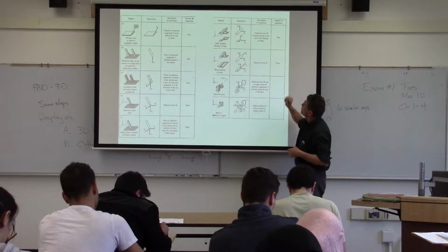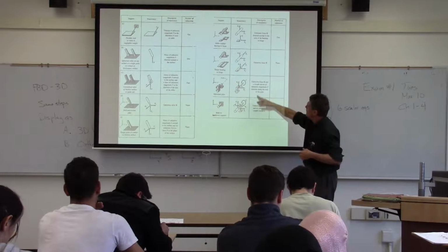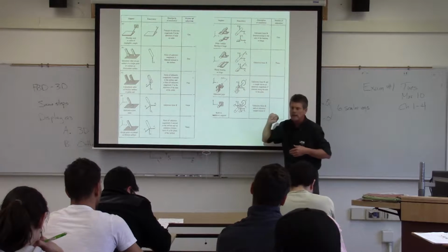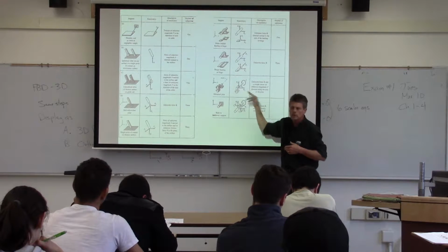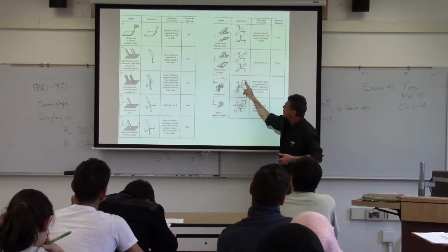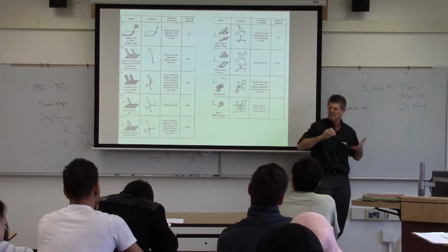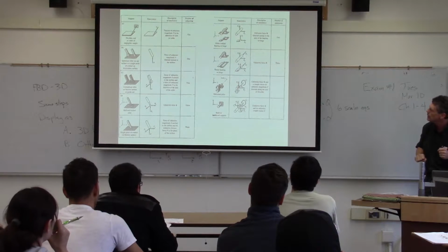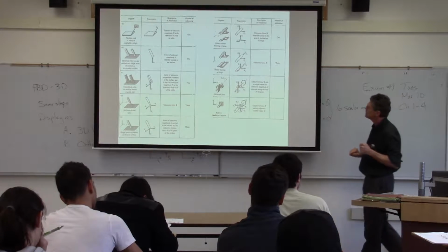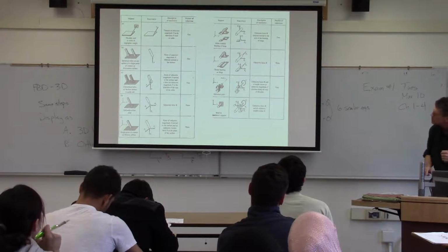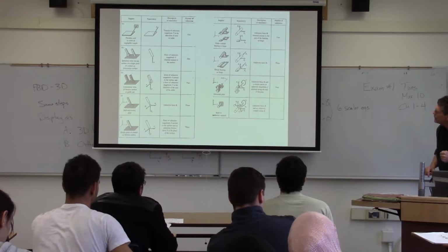So we'll end up having 3 unknowns there. And then a couple of unique ones. We have the universal joint there, which again provides me those 3 forces when I remove that piece there. But it also provides some couple. And again, that's like a drivetrain on a car and that sort of thing. We're providing some sort of fixed couple there. So we are going to have that potentially as an unknown. So we'll end up having 4 unknowns there.